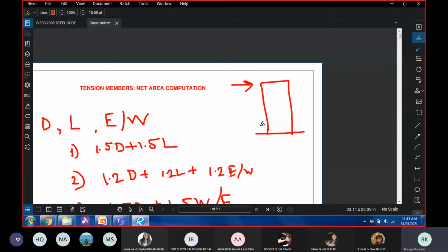Now, one of the phenomena that can happen because of the lateral load is that the structure might overturn. And the moment because of which a structure overturns is called an overturning moment. It's pretty straightforward. You have a bottle beside you, you try to apply lateral load, and it is going to try to overturn because of the moment that you're exerting.